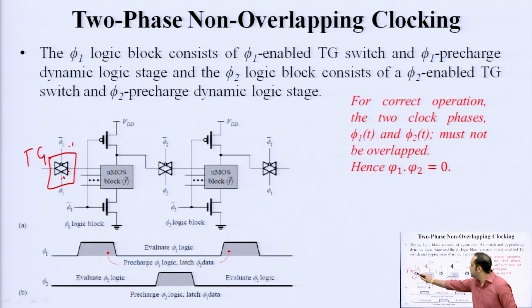So, you use TG1 here, say this is transmission gate 1 and this is transmission gate 2. So, this is switch 1 and this is switch 2. Again what you are basically doing is you are isolating successive stages from each other. When this switch is off, by off I mean when the switch is open. Okay.